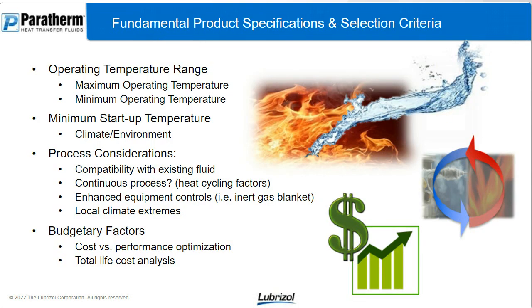All right, some of the fundamentals. Maximum operating temperature and minimum operating temperature. Obviously, that's going to be really important. You're going to purchase a fluid that's capable of reaching the maximum operating temperature. Also consider the climate and the environment that you're in, because that's going to determine your minimum startup temperature.